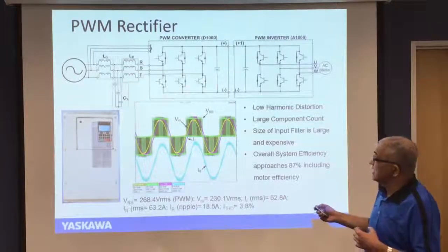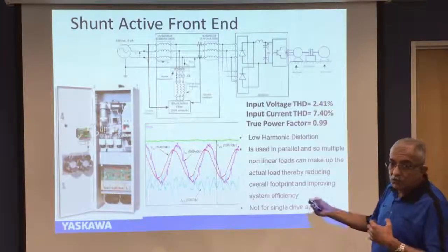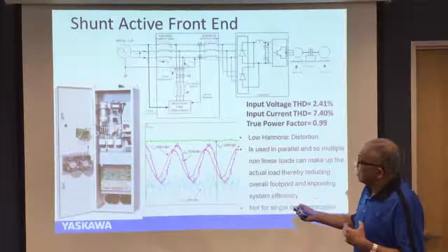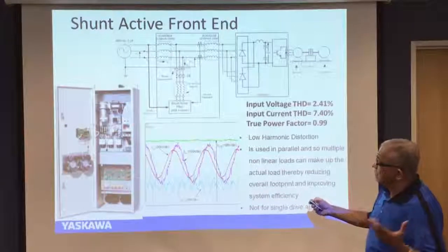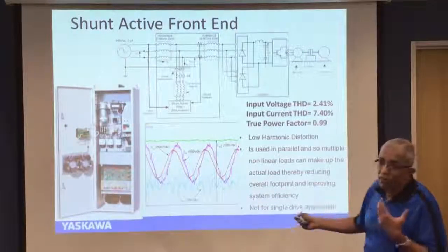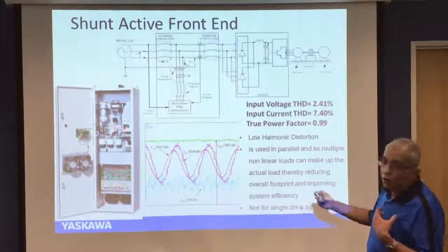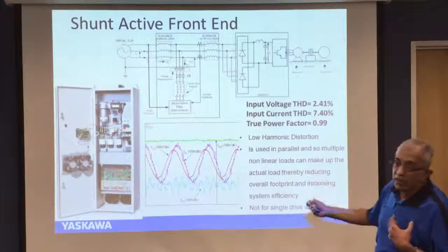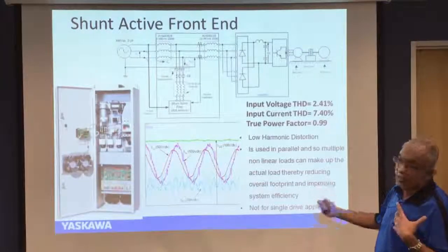But the concept is exactly the same, the same type of active filter is being used here, but it is used in shunt. And now you can see that the amount of harmonic correction it can achieve is much better than the previous scheme. This can be rated to 1/3. The actual power which we need is typically 1/3 of the load, which means that though this is a 90 amp module, it can do harmonic corrections for up to 270 amps of nonlinear load connected.